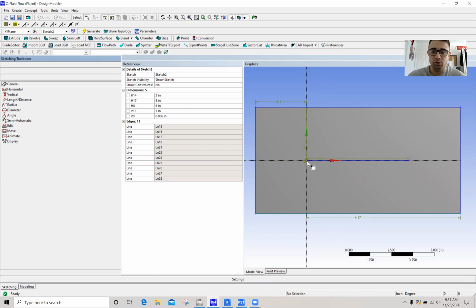Make sure initially that you know your coordinate system, because when you move to doing lines or specific lines to show the boundary layer, you need to know the coordinates in meters. So make sure to take notes on that. Let's see here. Also, I'm seeing it's 0.006, not 0.06. Messed that up a little bit.